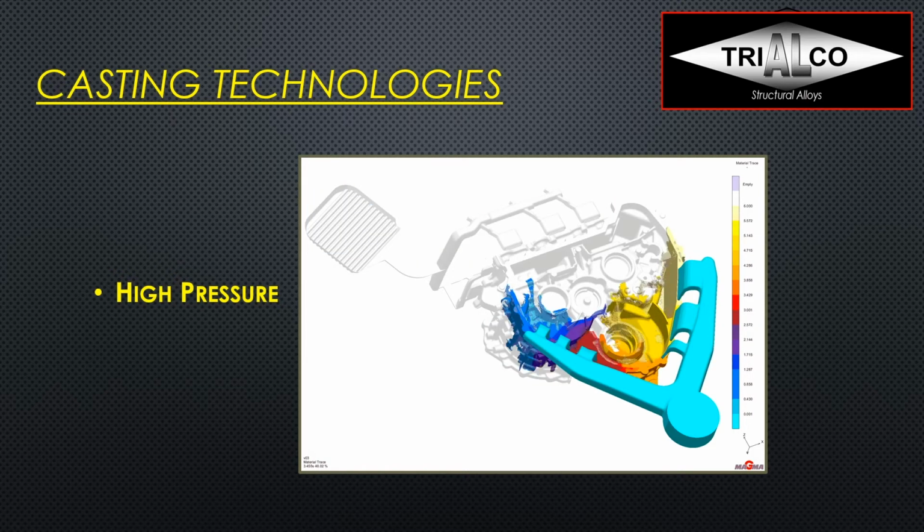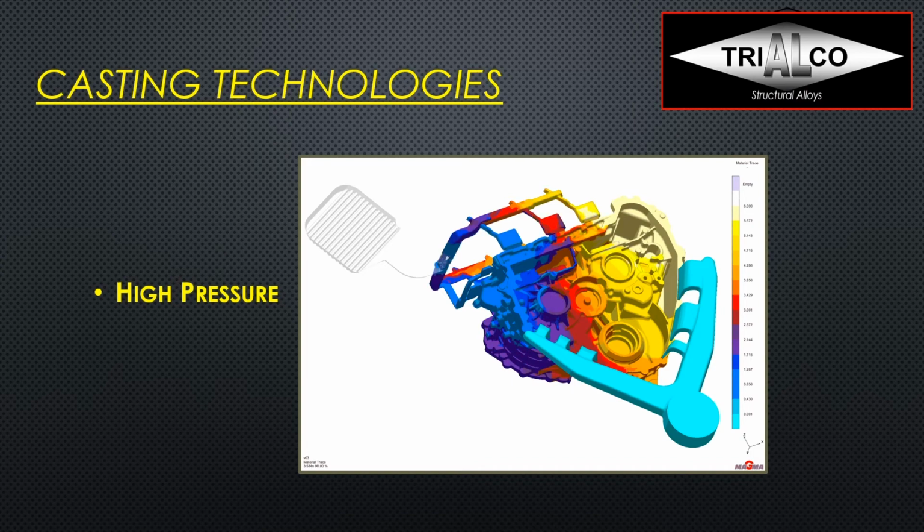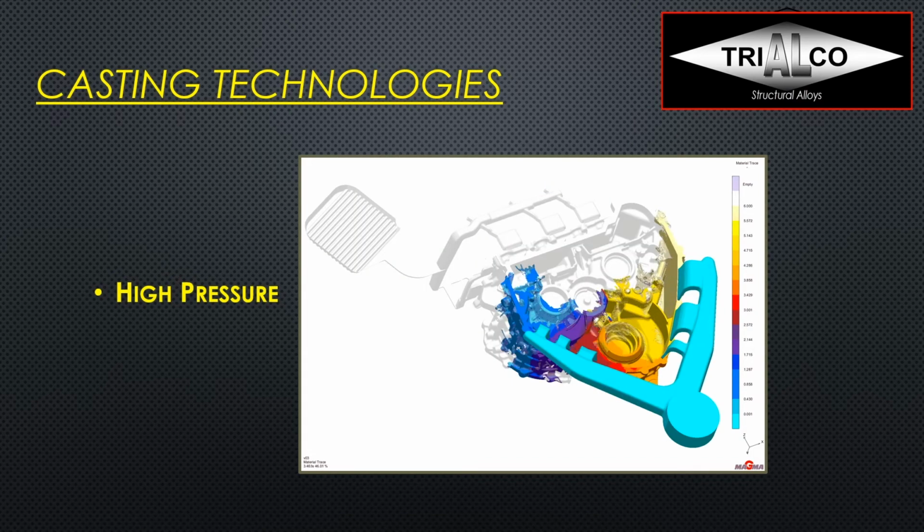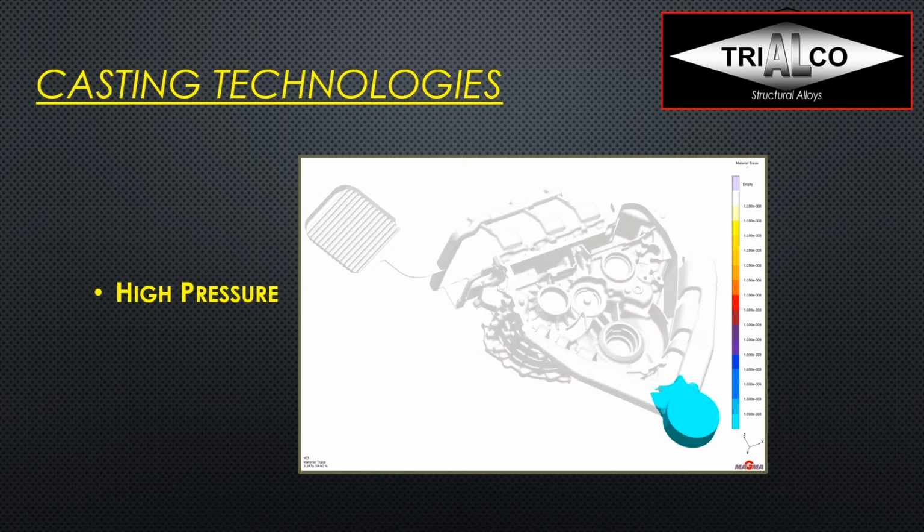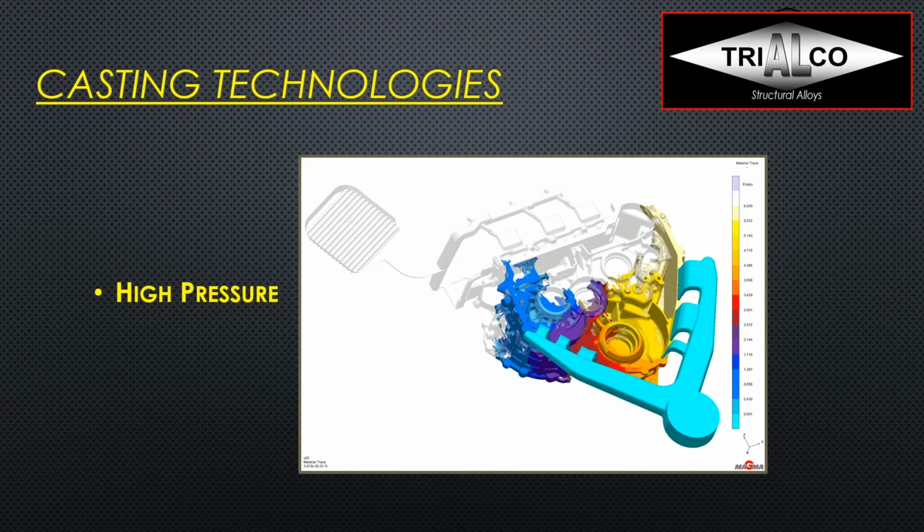And then the metal goes into overflows, and in this case, a chill block where we naturally vent or pull a vacuum. And so after that comes the third phase. So we had the slow shot, the fast shot, and now the intensification phase, which is where we put the really high pressure, because this is where we compensate for the metal solidifying and therefore shrinking in the cavity.